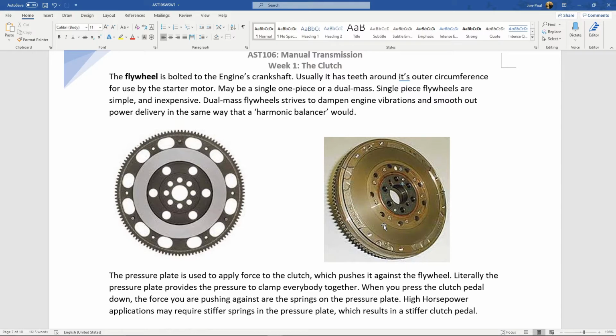So some vehicles, let's talk about application here. This is going to be your Lexus's, Lexi, is that the plural? This would be your Volkswagens. These would be your commuter luxury vehicles. They are going to have a dual mass flywheel to try to smoothen everything out. And then your Sentras and Versas are going to come without. So me, race car, I want the guy on the left. If we're buying a vehicle for your wife, we want the one with the dual mass on the right.